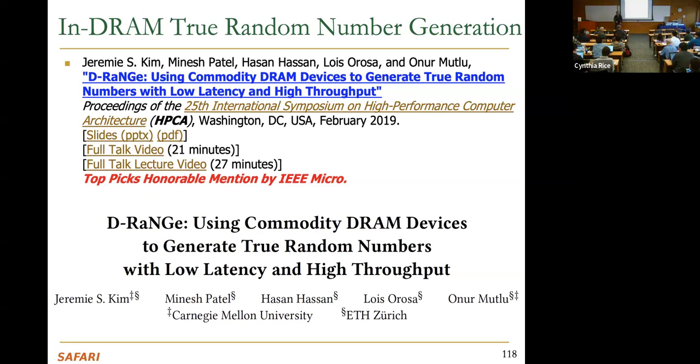Yes, we do look at it. Precision is important. The difficulty is that in some of these cases, very high precision is very difficult because of the bit serial nature of this. Yeah, people are working on it. People have proposed, building on some of these works, adding floating point capability inside the DRAM, but that requires a little bit more area. I'm not suggesting this is a good fit for every type of operation.